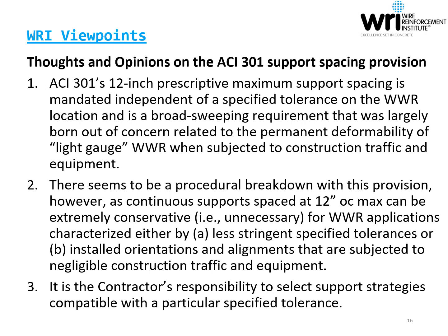In the absence of a specifier's definition of a particular application's reinforcement location and its accompanying tolerance, as well as an absence of insight into how a particular placing contractor decides to deploy its means and methods, how does ACI know ahead of time what the maximum support spacing must be? How can there be a mandated output without project or application-specific input and decision-making on the part of both the specifier and the contractor?